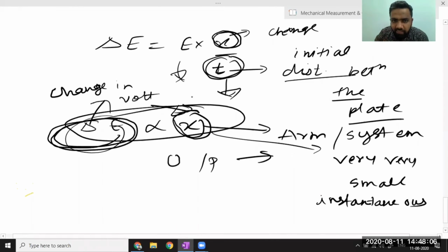Now, the capacitance system is using voltage, but all the things are correlated. I have used the capacitance method only, C1, C2, all these things. What I have tried to deduce is that whenever the capacitance is changing, or the distance between the plates is changing, there will be a change in voltage which can be detected automatically. Is everyone clear?